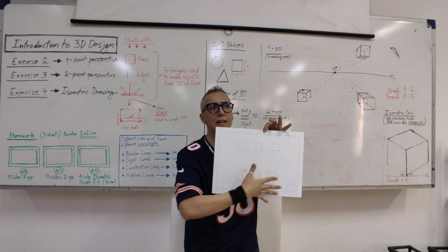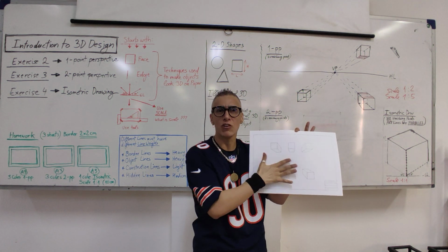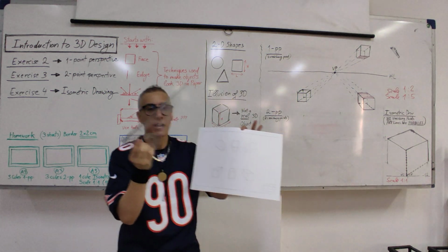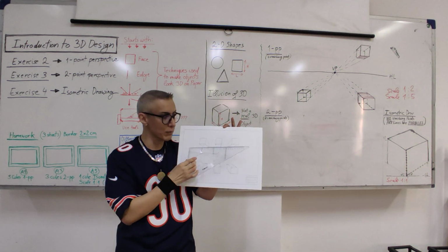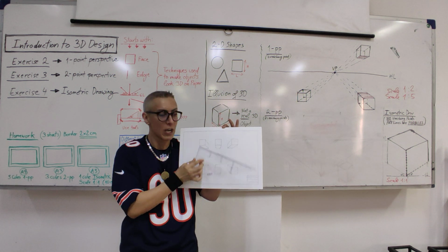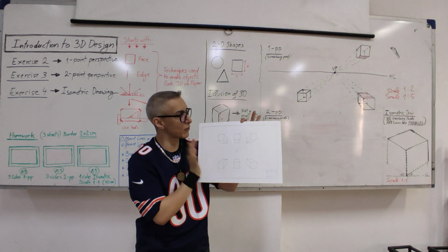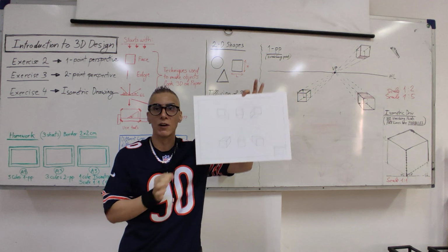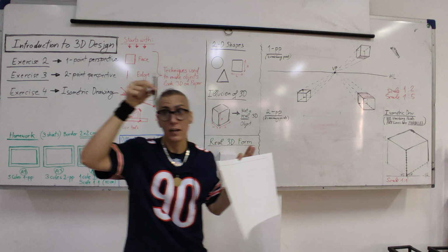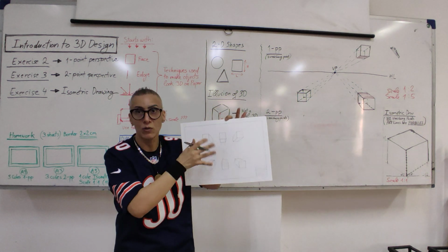Another thing, the cleanliness, how clean it is. I don't want to see deleting, smudging. Be careful your hands to be clean, the rulers to be clean. If you draw something with a ruler, never smudge the ruler on the drawing like this too much. Pick it up, put it here, okay? Pick it up, put it, so that it doesn't create smudges. This paper has to stay white and perfect. Only these lines have to be seen. And remember, this must stay 90 degrees when you draw with it. Otherwise, the lines will also not look good.